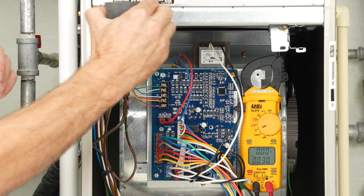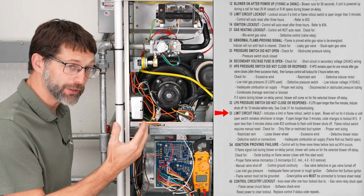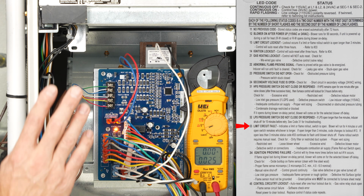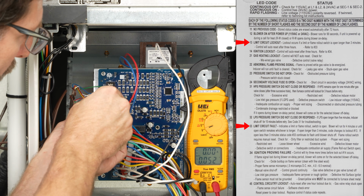So what we do is, if we were to turn the power off and turn it back on, you're going to see a number 33 error code. So 3 short flashes, 3 long flashes. Now with a status code light of 33 or 13 indicating a problem with a limit switch,